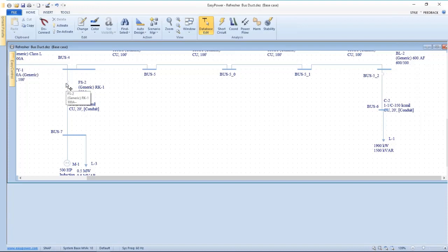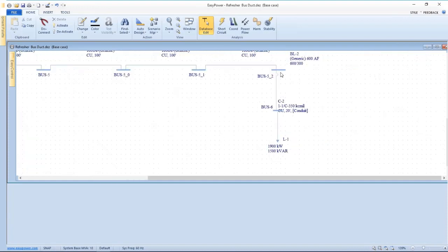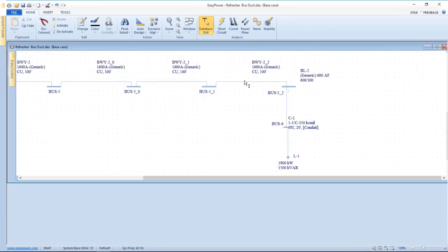And as far as downstream, I'm using the largest load, which would have the largest protective device at each of the drops on my virtual bus to give me the loading that's going to be downstream. So that's what I would label the equipment, and then I'd have, again, much higher energies calculated and basically, don't work on the bus duct while it's hot.